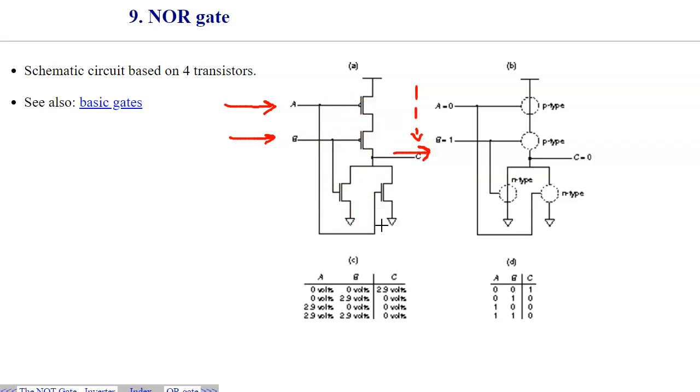circuit or this gate, partly because you can see that the connection of our output is not made to any gate terminal of any transistors. These are connections to the drain and the source of P and N type transistors. So basically, we always view gates as one-directional devices. We have some inputs right here, and there could be circuits that have multiple outputs, but gates typically have just one output signal.